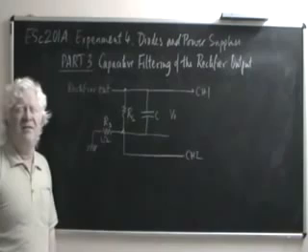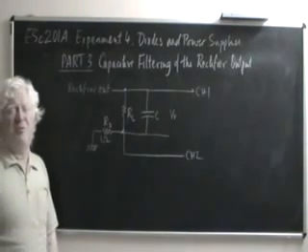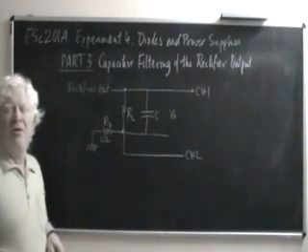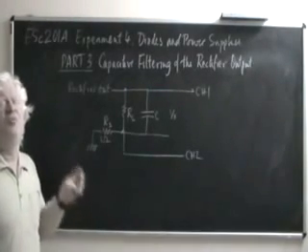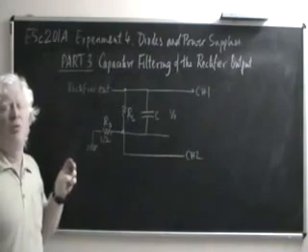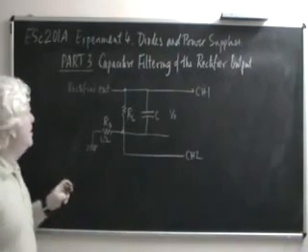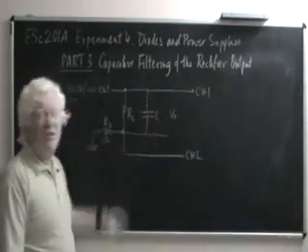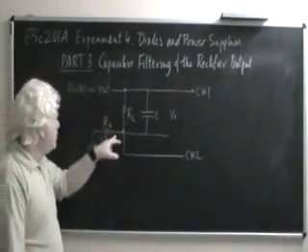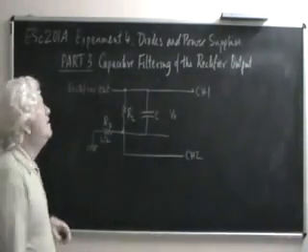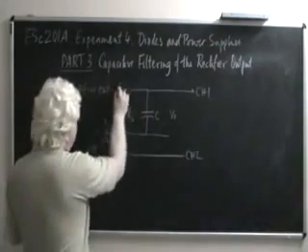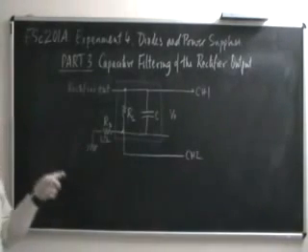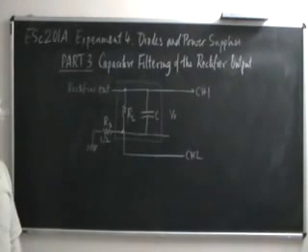The series resistance is required to make current measurements. It is very interesting, and we will come to this in a moment, that the current flows for a very small, minuscule portion of the cycle. And the current doesn't just flow through the resistor, it flows through the capacitor as well. So the current that actually flows through RS is the net current taken by this entire portion of the circuit. And that is what will be of interest to us to understand.